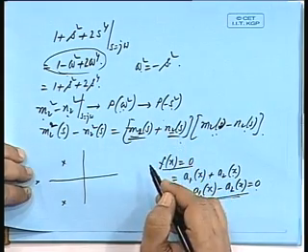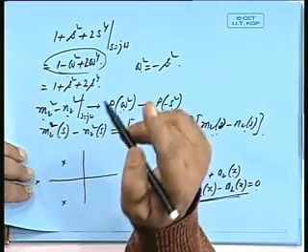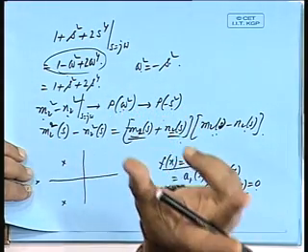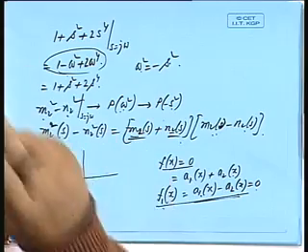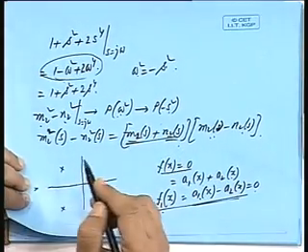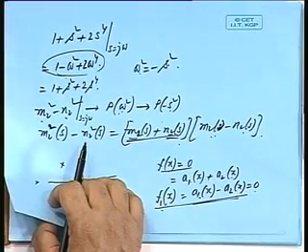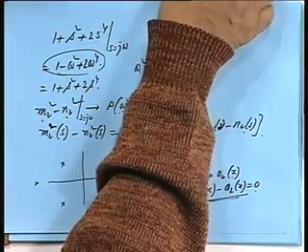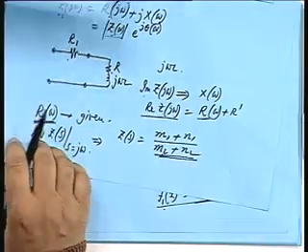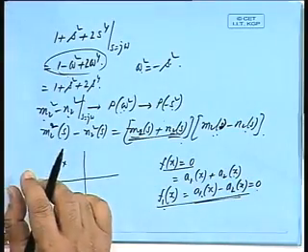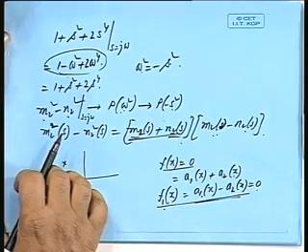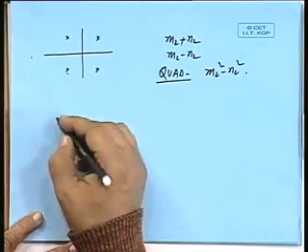Why left half plane roots? Because the original function Z(s) is a positive real function which should satisfy the Routh-Hurwitz criteria. That means all the roots of the numerator and the denominator must lie in the left half plane. So m2(s) plus n2(s) corresponds to the function Z(s). It is the denominator of Z(s), is it not? Which is a realizable function. So the roots here are lying in the left half plane. So you select out the roots corresponding to the left half plane. Once you have done that, then m2(s) plus n2(s) is defined.